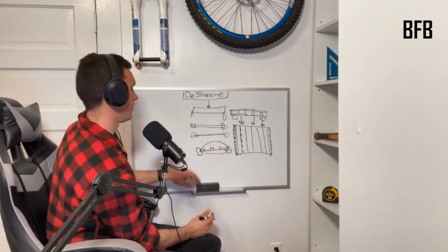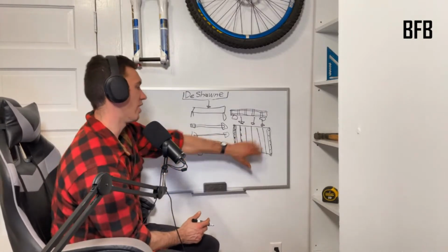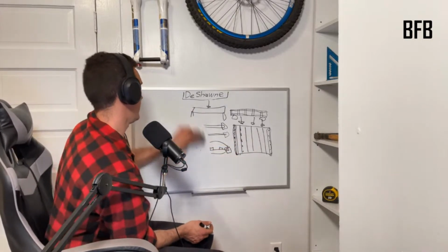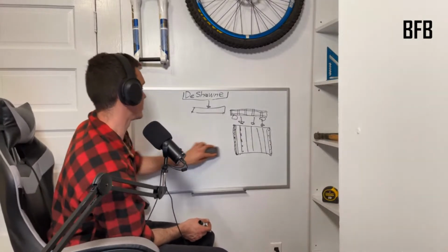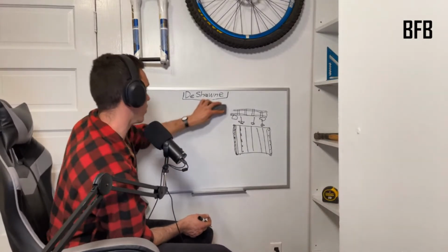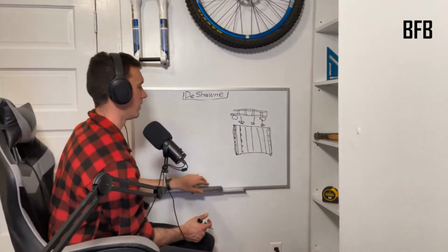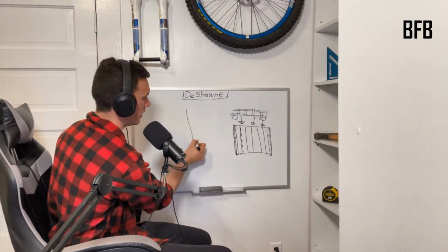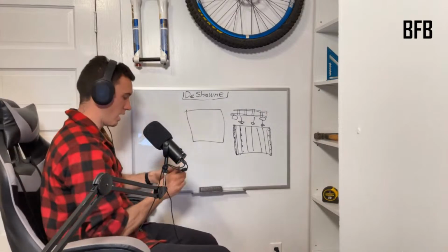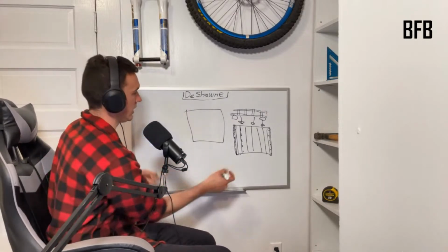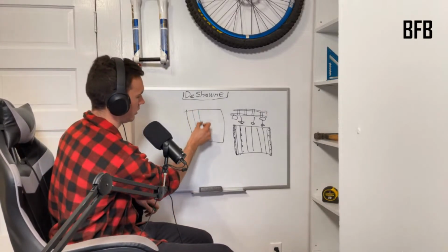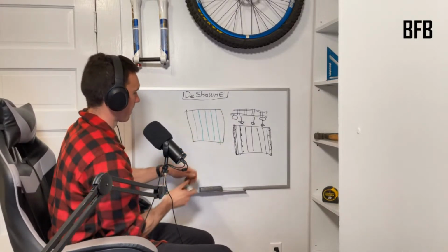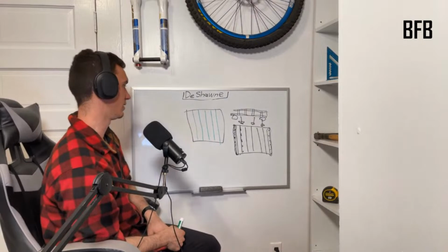And you know what? Speaking of ceiling joists, if you were framing a room like this, you wouldn't put a ceiling joist on the wall. That'd be dumb. You don't put ceiling joists on walls because the whole point of a ceiling joist is to support weight spanning from wall to wall. If it's got a wall there, you don't need a ceiling joist. So if I had a room and that room was a box, and if I had another color, which I do, and that color was green, and the green were ceiling joists, and the ceiling joists were happy, all right, that's where I'd put my ceiling joists.